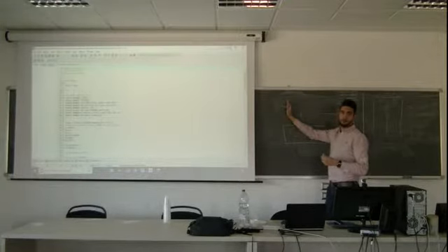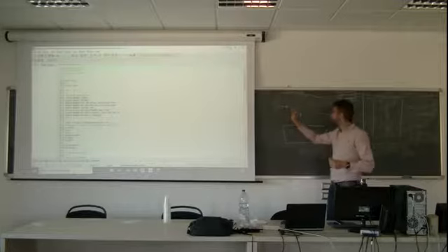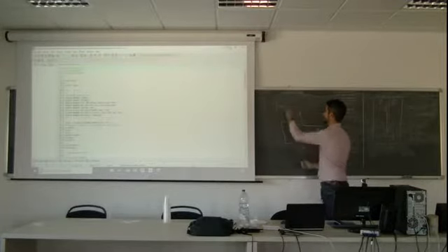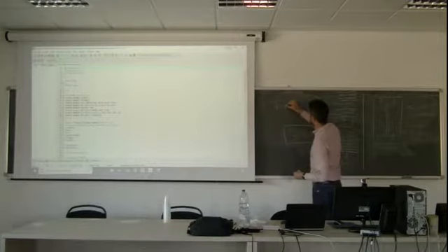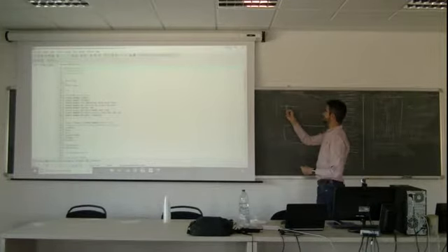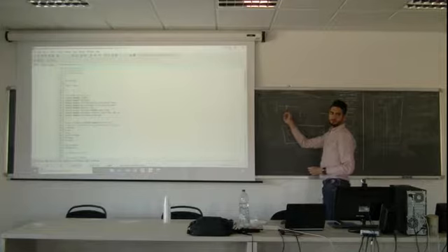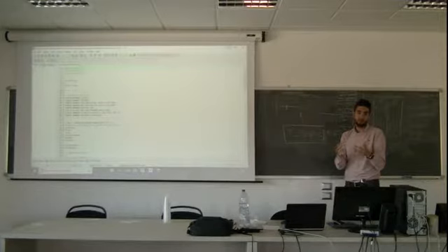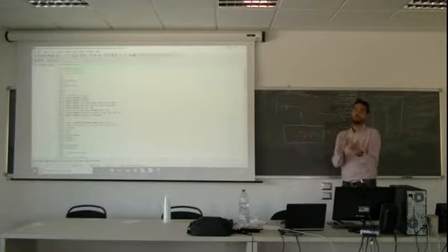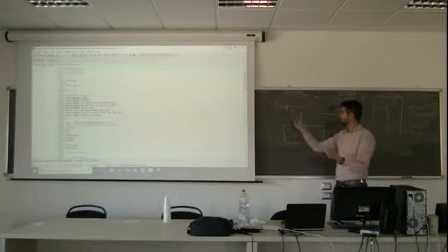If you don't relax, it can happen, if your physics are not very simple, that you stay like this. And you don't get to the solution. And you don't converge. You stay jumping over the solution. If you relax a little bit in the energy equation, you will get it.